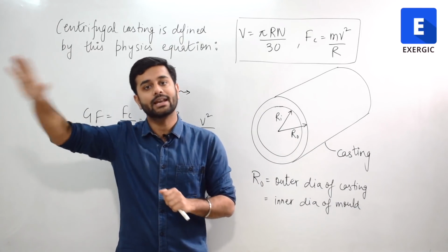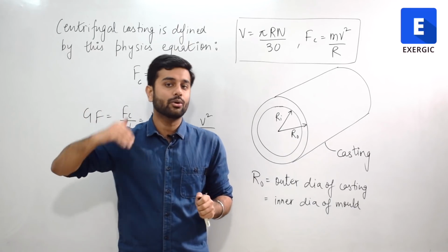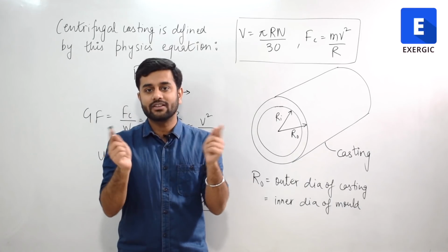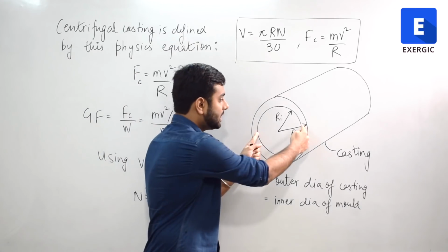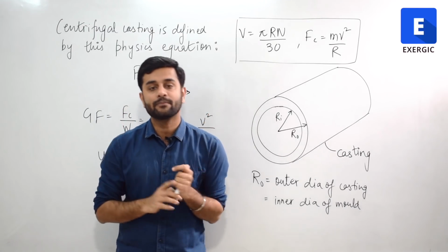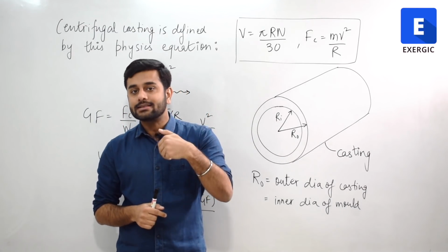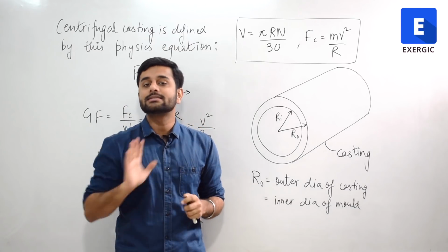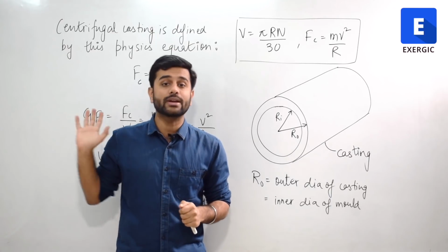I am not going to any other random sources; you can go and check yourself. As far as I can remember, the two values given in the question are 230 inner dia and 250 outer dia. So the thickness is 10 on each side, which is much less than 7%, roughly half of that. So it definitely is a thin cylinder that we are discussing in the question.